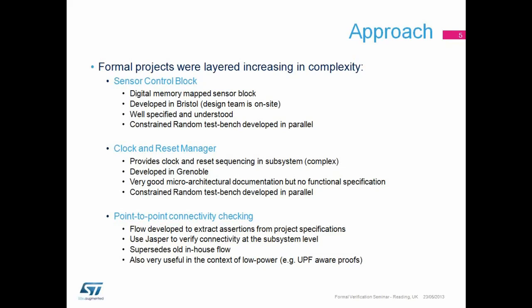Reset Manager. What that does is provide clock and reset fan-out within the subsystem, also in the context of things like operating point transitions. When you want to move from low power states to high power states, or from retention modes to normal running, that block handles those timing transitions as well. The block was developed in Grenoble, and it was quite an interesting case because we didn't really have a functional spec for it. It's very critical and very complex.